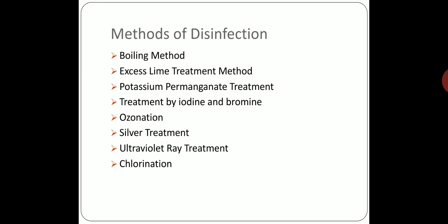If carbonation is occurring, that can be removed by a process known as recarbonation. And the dose that we apply of this lime to water varies from 10 to 20 ppm. 10 to 20 ppm means 10 to 20 mg per liter. We apply lime to water.